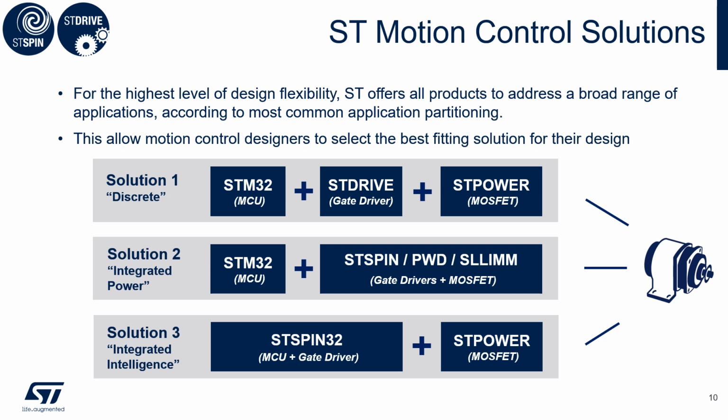The second solution is the integrated power solution. This means we have also a standalone microcontroller, but we have a gate driver where the MOSFETs are combined in a system and package approach or monolithic approach.